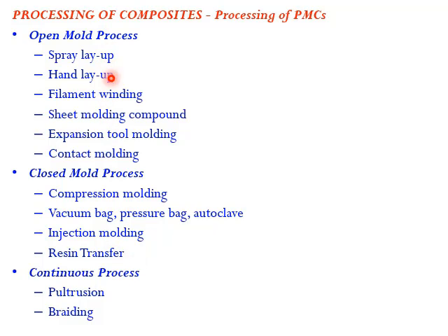These open and closed mold methods are one way, where we have to wait until a product is cured before we can load a new one. It is not a continuous process. If you want a continuous process, then we go with pultrusion or braiding.